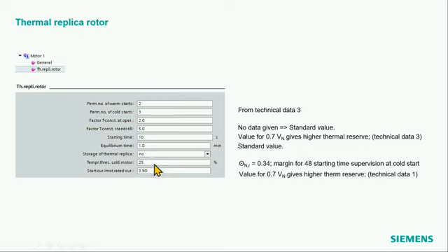So it's a compromise when to apply the shorter time for the warm motor, the maximum locked rotor time, and when I take the longer time here. So I go away from the 34. If I set this to 0, then I will always apply the warm motor time. So this will then also always be warm. Then I have the shorter time. So here I make the compromise going down with this threshold between 34% and 0, somewhere in the middle. Okay.